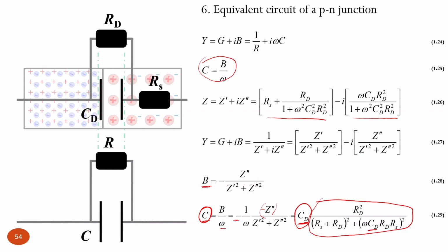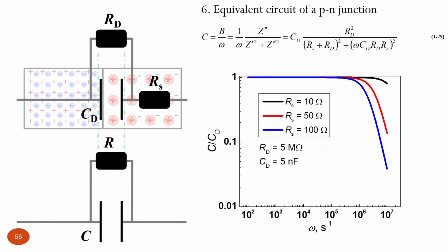So that's where the problems come, and unfortunately in the field people quite often do not take an appropriate approach for measuring depletion layer capacitance. They just measure it at a certain frequency and provide the value. That is a mistake, because it is actually not just a value, but some frequency dependent function. So that's how it looks.